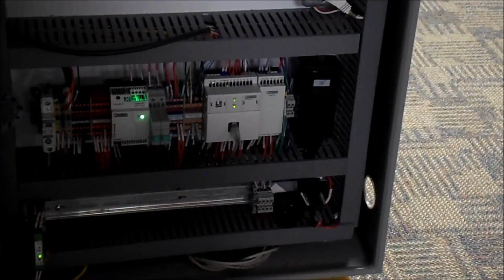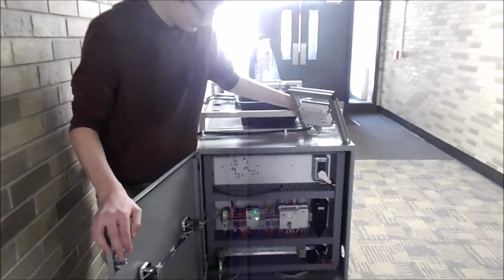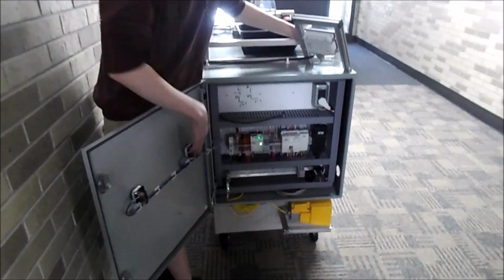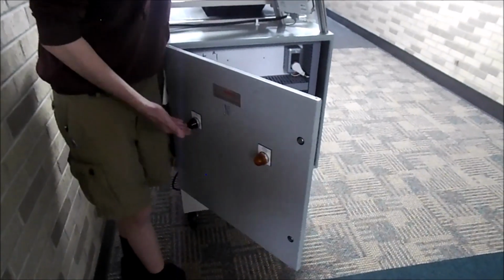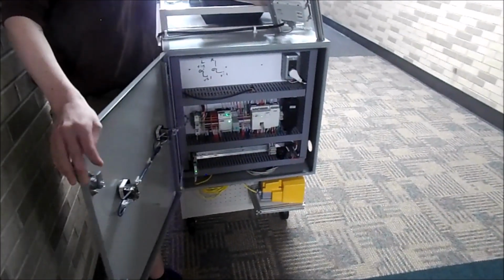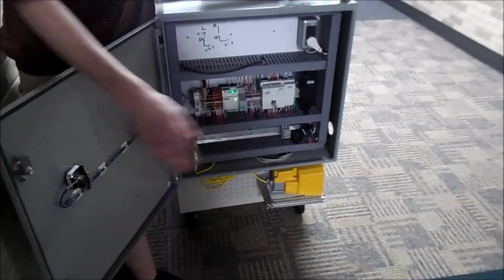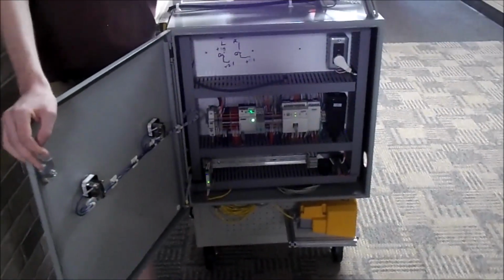Down here is a large relay, which we have one mounted inside the shredder controlling that, since the amperage rating on the Nanoline controller is too low to control such high current draw components. There's also lights, which we use as warning and positive light mounted on the outside of the box, and a load reversing relay which controls the press of our machine.